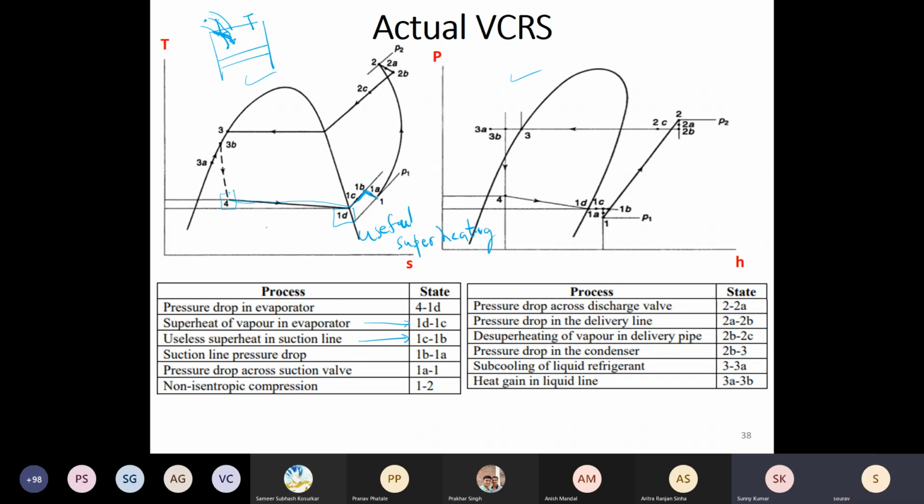Then what we assumed was an isentropic process during the compression process. Okay, definitely it will not reach this isentropic point. You will reach somewhere on the right hand side, and the process itself need not follow the particular path that we draw, something of that dotted line. It can follow any arbitrary path, because in this process there is also heat transfer. Okay, so this line itself is again just an arbitrary line, just to show that we don't actually know the process.